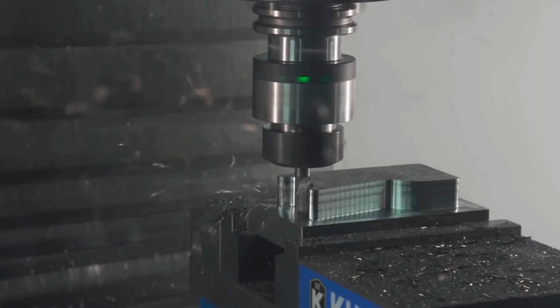So let's look at the 3-axis functionality. With 3-axis functionality, you've got access to adaptive clearing, horizontal parallel, you've got contour and ramping on the Z level finish, as you can see in there. You've got spiral and morph spiral, radial, projection, morphing, scallop, pencil tracing, and you've also got the 3+2 machining on it.